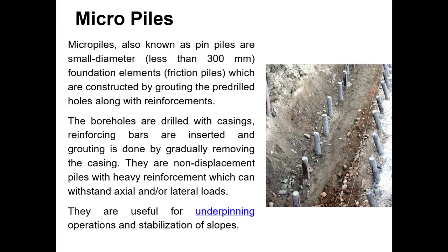The boreholes are drilled with casings. Reinforcing bars are inserted and grouting is done by gradually removing the casing. They are non-displacement piles with a heavy reinforcement which can withstand axial and/or lateral loads.